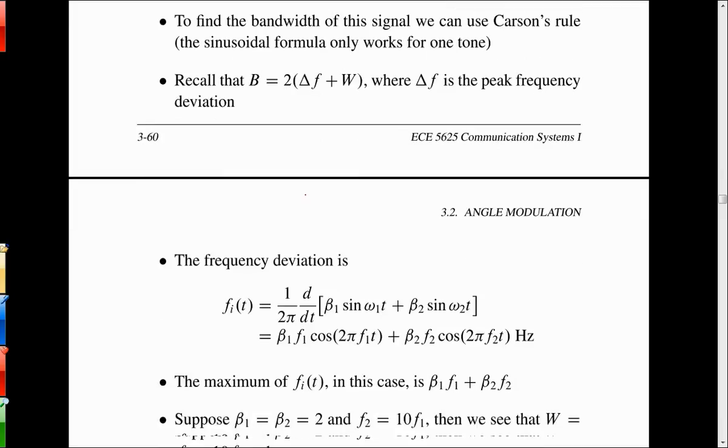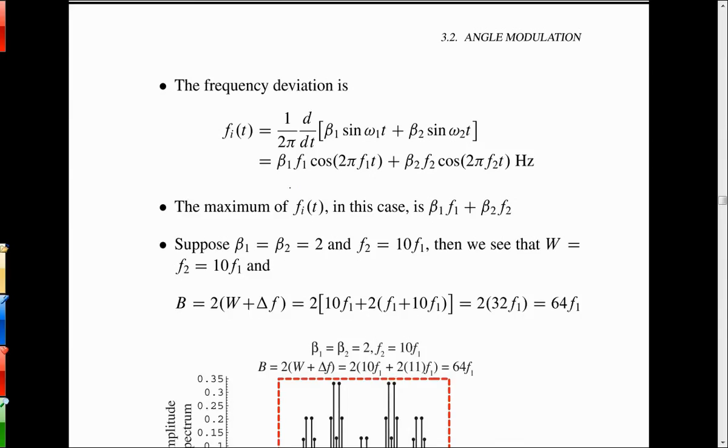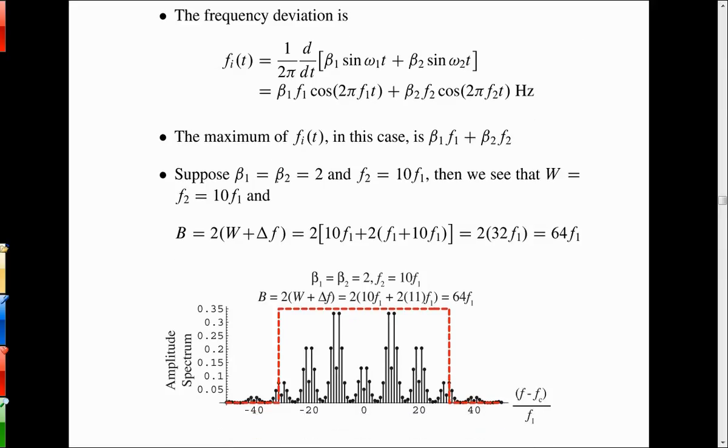But this sort of analysis is actually done in one of the telemetry standards that's used by the Air Force, the system I've been working on called the AFSCN, Air Force Satellite Control Network. It relies on subcarriers, and it relies on phase modulation of the subcarriers, and these things with the Bessel functions are actually part of the math that's behind all of it. Not just invented today, but invented about 30 years ago. So this is not a new thing. This is just a snapshot of the spectrum now.